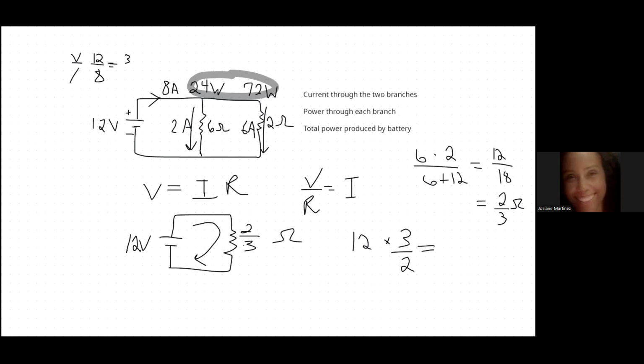When you say a circuit is equivalent, that means the voltages that you're getting and the total current coming out of that source are going to be the same. So the error happened here when we calculated the total resistance. Must have been a typo of some sort or a brain freeze, but this formula requires that you use the same values for the resistors R1 and R2 in the top and bottom.